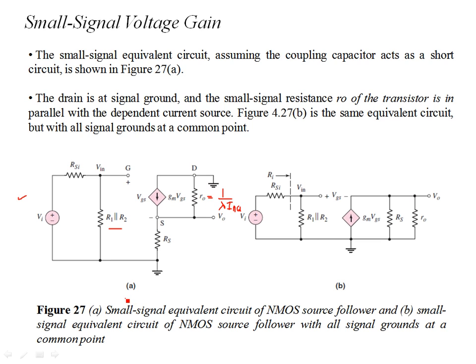Now this is an AC equivalent circuit model of the transistor, consisting of the small signal equivalent circuit of the NMOS transistor in a source follower configuration. Figure B and figure A are equivalent circuits, but in figure B, if this is the gate terminal, then this VGS means that this is the source, and you see the direction of the current is the same, coming into this terminal. You have created a common ground. So this is my drain. It makes more sense that this is a common drain, CD configuration of the NMOS device.